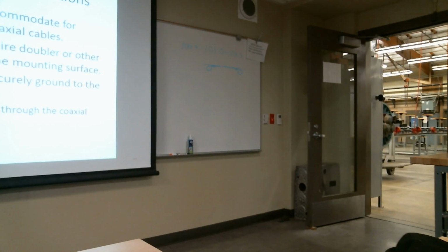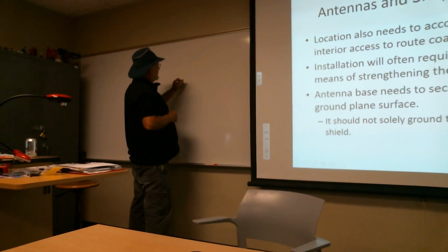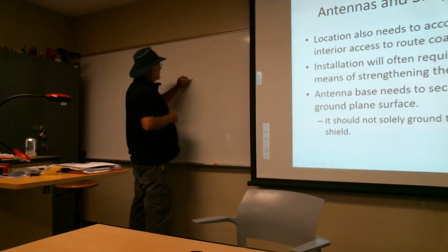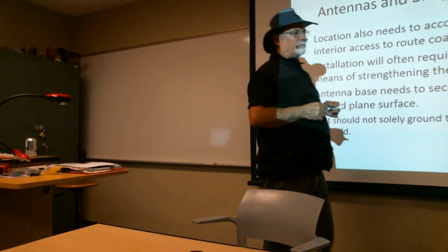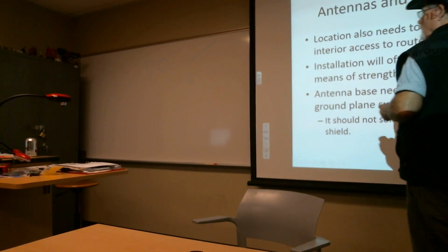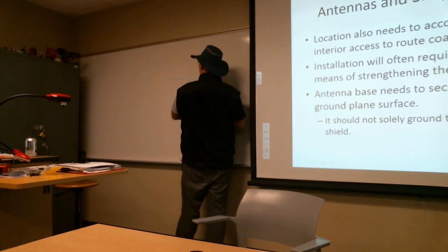The antenna base, there's really two basic kinds of antennas that mount. There's one kind that comes down like this, with a nut, and there's sort of some insulators that sit in here, and that's an unbalanced antenna lead. So, monopole antenna. Somewhere in here, you're going to need to make a ground plane.